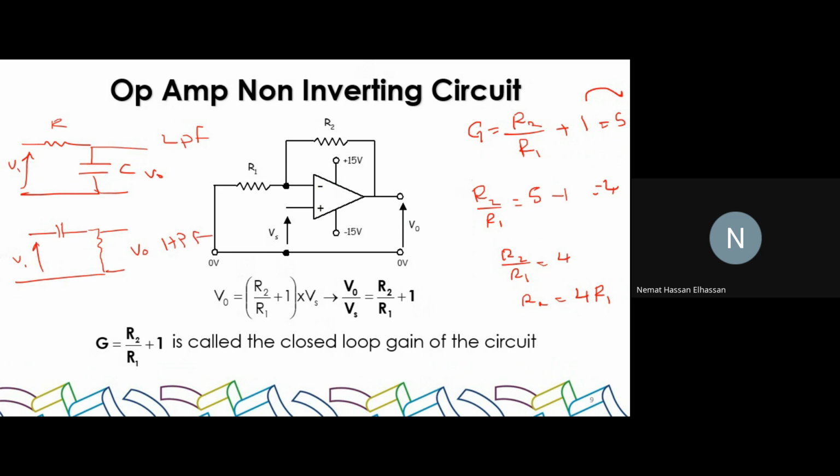If you want to build a band pass, you'll take high pass and low pass and connect them in series. Okay? This is just a quick recap of what we did without further details because we don't have time for the details, just to help you through. And these are passive, they have no op amp. These are passive filters. All they do is filter the value of the input based on frequency.